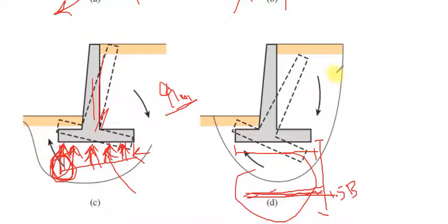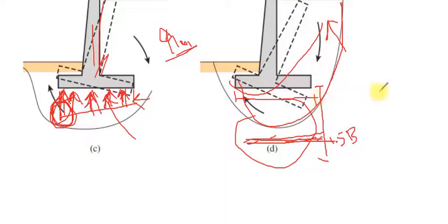The shear failure may start from this point, and all of this wedge of the soil is filled, and we may use light backfill so that the soil under the base of the foundation can resist the high load applied and coming from the retaining wall. Also, we have to check if there is a weak layer at a depth of about 1.5 B.